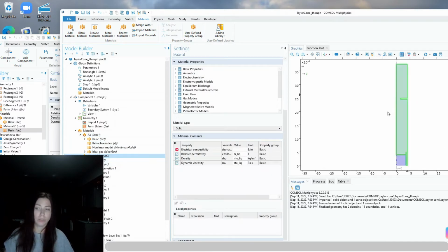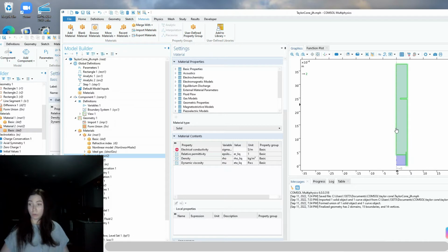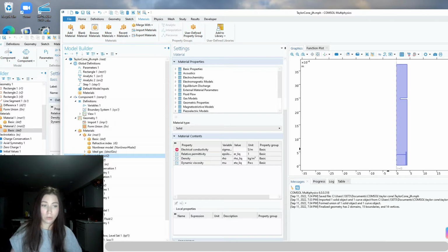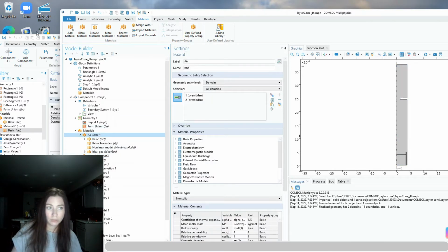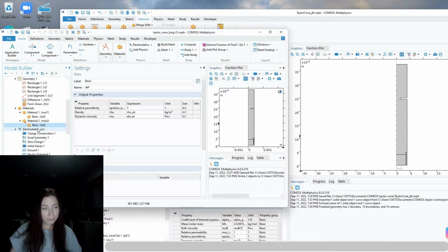So the thing is, we have a deforming boundary, right? So technically the liquid is material 2 and this is air to begin with, but at some point the liquid boundary deforms, so it goes into this domain. So we're just defining material 2, or the charged polymer that will be electrospinning through the Taylor cone, as the entire domain 1 and 2, and air won't have any selection. Hopefully that makes sense more as we go.